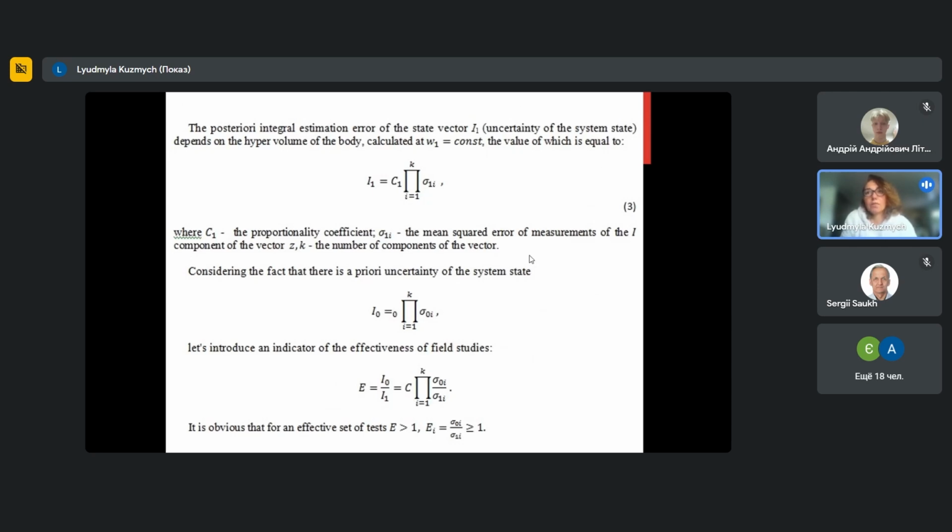Verification of the methods of standard instrument consists of the fact that a calibrated signal is applied to the verification instrument system, the value of which is automatically set by measuring device of the instrument system to the verification mark of the scale. This signal value is measured by reference measuring device. The value of the signal from the measuring device and the sample is processed using a computer in order to calculate the metrological characteristics of the calibration device.